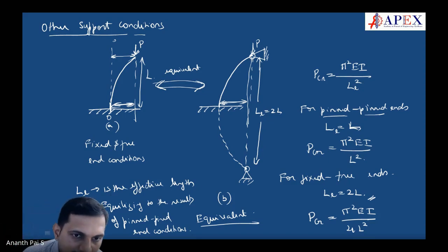No. See, deflection is the same. In the free end, this is like this, is it not? After it has deflected, we see that it is almost half the pinned joint. You see the curve which is there. This curve is similar to half the pinned buckling, is it not?